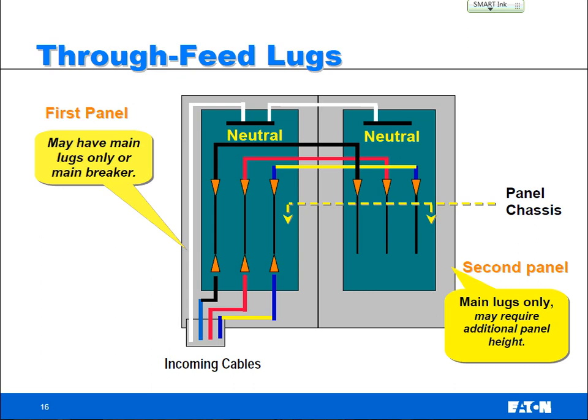From a design standpoint, if these 2 panel boards come out 6 inches apart from our engineering side, we may default to making the second box bigger so both panel board boxes are the same height. That really gives a much better appearance for the owner, but it also allows these cables to shoot directly across from lugs on one side to lugs on the other side, for example.